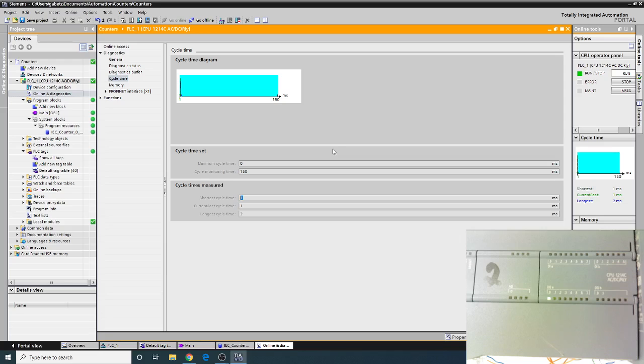All right. But my point here is this is a counter that is really overall meant for slow changes, right? It's not truly meant for absolutely rockin' high speed. Now, there are counters built into this PLC, but not most, that are called high-speed counters. And their whole job is to count things at high speeds, all right? So if your program is 1 millisecond, we could, in theory, count 500. And that's assuming everything is a constant pace, all right?